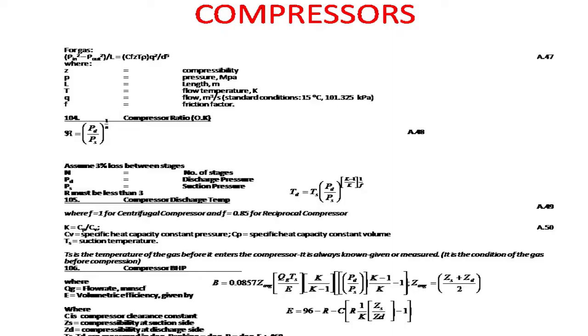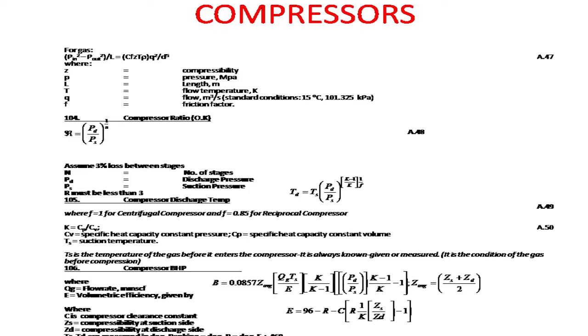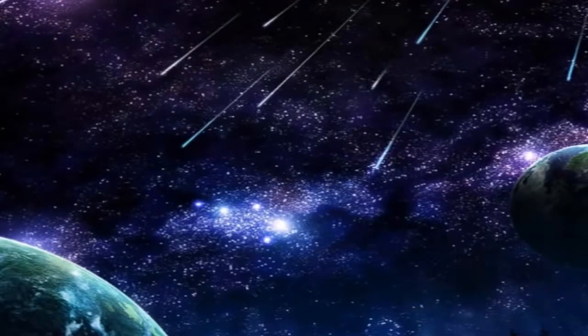Now, we want to size compressors. There are formulas by which we do that. Now, that's the formula for sizing compressors. Once you know the ratio, the suction pressure, and the discharge pressure, you can calculate the number of stages in a compressor by this formula on the board, where R is the ratio per stage. You can say, okay, I want a ratio per stage of 3, or I'll probably give you 2.5, but it will not exceed 2.5. Then we can say, okay, we want to get the number of compressors.